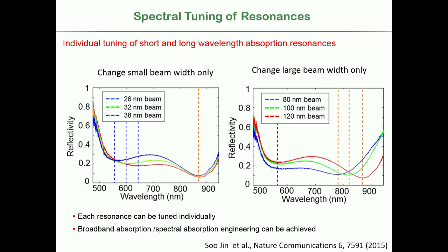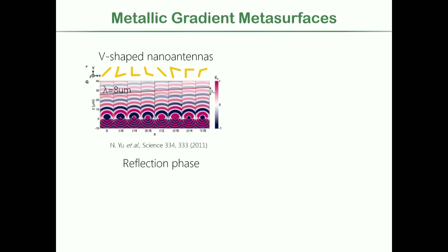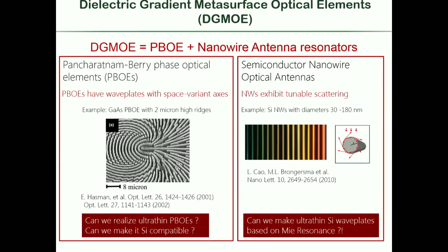beam. So I want to close with one last image. I'm told I should finish up, and that is a very complex arrangement of dielectric resonator structures. So here's a structure that most recently we started working on. It has about 20,000 different silicon beam antennas, and there's a gradient in the orientation of the silicon beams. And by making gradients in the orientation, size, or shape, we are now able to manipulate wavefronts, and there are a number of groups that are actively working on this.